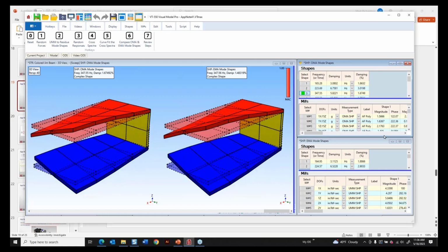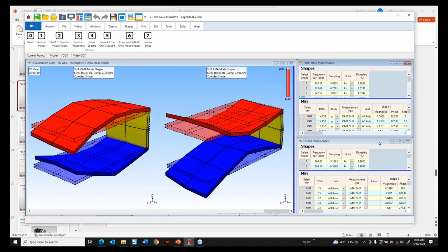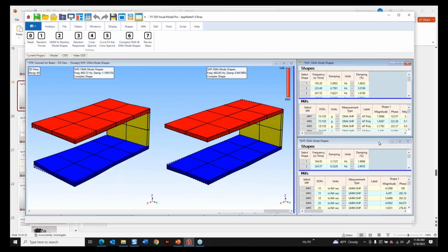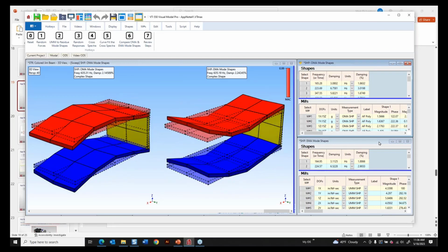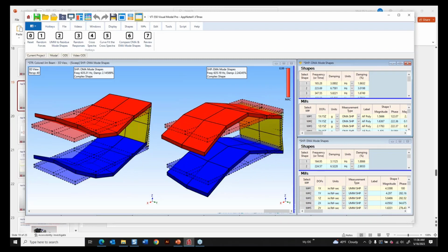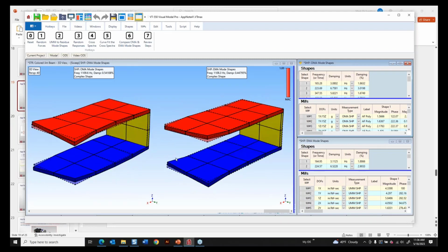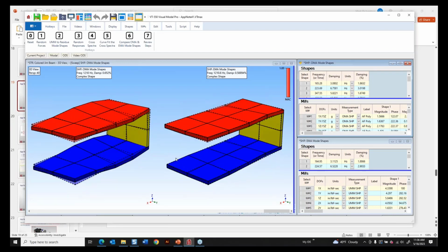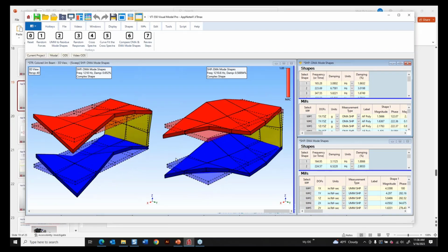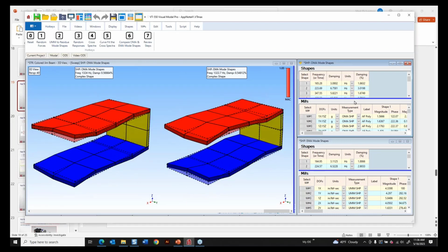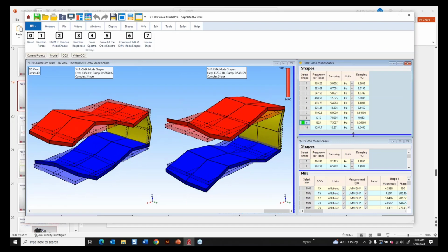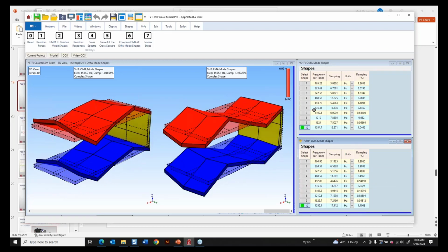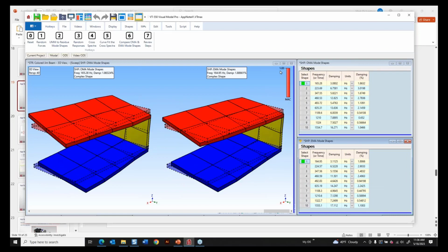Quite different values. So if we were to display the SDI value for these different mode shapes, it would be 0 because their magnitudes are quite different. But the MAC value is very useful for just saying, yeah, this is the same mode shape, even though it's scaled differently from one set of data to the next. These are the same mode shapes because the MAC values are all very close to 1, 99%.